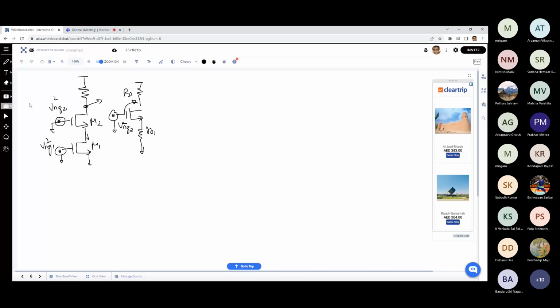So now if we look at the load, one thing is that, compared to the common source amplifier, we are getting a better bandwidth. That is one advantage of this particular configuration, and it can be used in differential versions also wherever there is a need for enhancing bandwidth. Now, if rather than bandwidth our priority is to get better gain, and I apply an active current source load, how does it change?